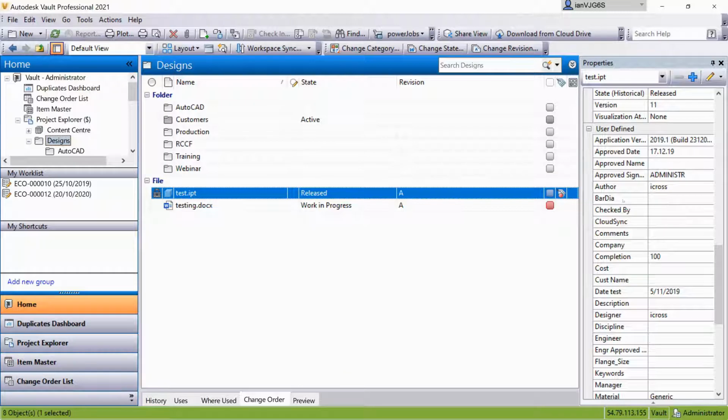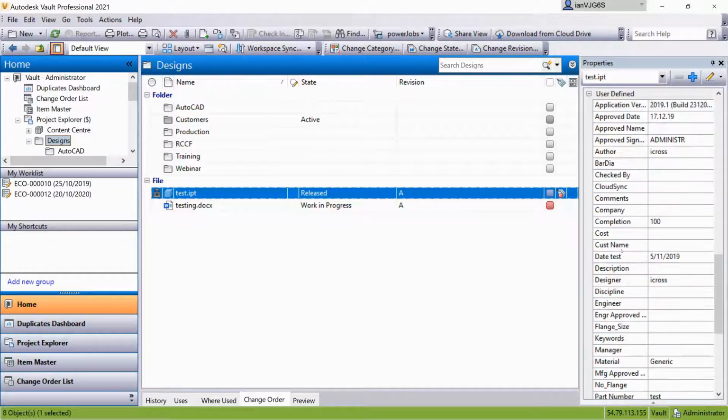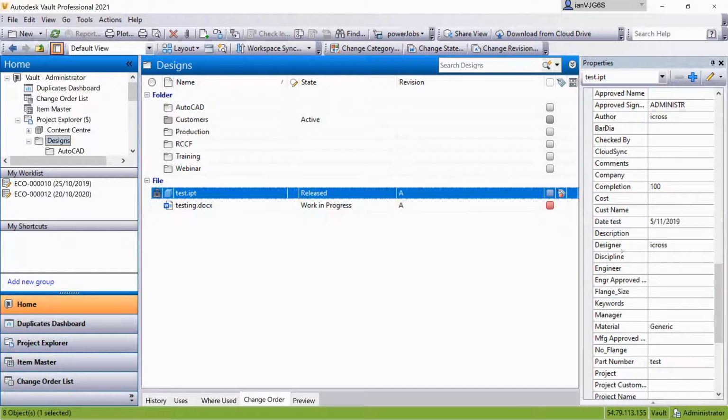Now, you can have as many of these as you want. But with Inventor and AutoCAD, with Inventor, it has to be an iProperty. With AutoCAD, it has to be an attribute. You can't just link it into plain MText. And with Inventor's title blocks, it can't be a prompted entry. It has to be an iProperty or a custom iProperty that you have to link it with.